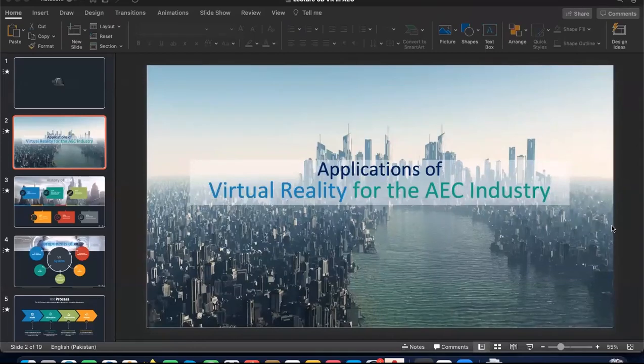So what you do, in many software like even Pix4D, there's an option. You go on the software and click that point, because this plus sign or the cross sign is also visible in your survey. You click on your cross point, measure, and manually enter these 8 or 9 or 10 points.